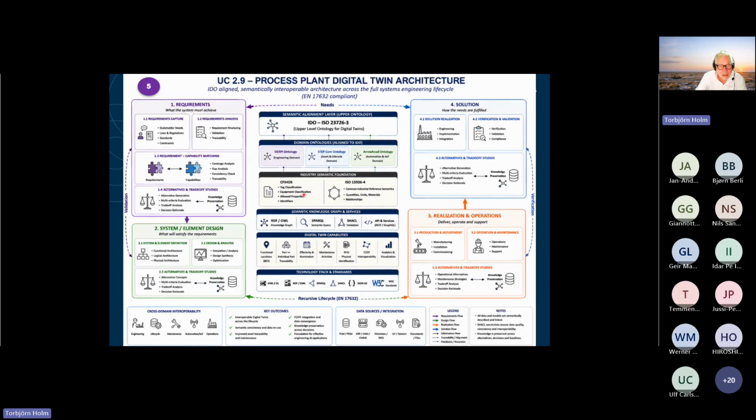We are using classification schemes from CFIHOS. CFIHOS is based on ISO 15926-4, and that is tag classification and equipment classification. So tag is classifying things here. Equipment classification is classifying things there and there. But it also specifies allowed properties for this and for this, and they are different because these are the physical things, and these are the requirements and the specifications, identifiers, and so on.